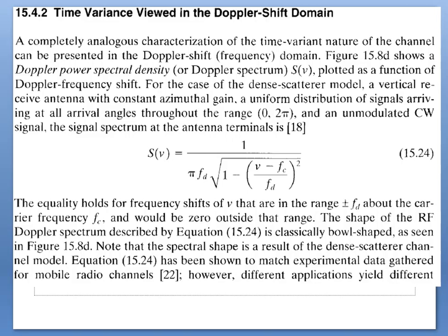Note that the Doppler spread Fd and the coherence time T0 are reciprocally related, resulting in an approximate relationship between the two parameters, given by T0 equal to 1 by Fd. Hence, the Doppler spread Fd is regarded as a typical fading rate of the channel. Earlier, T0 was described as the expected time duration over which the channel's response to a sinusoid is essentially invariant. When T0 is defined more precisely as the time duration over which the channel response to a sinusoid has a correlation of at least 0.5, we already discussed it.